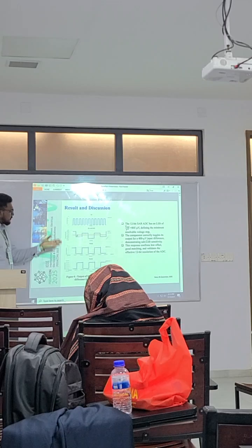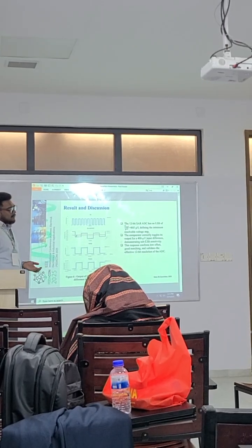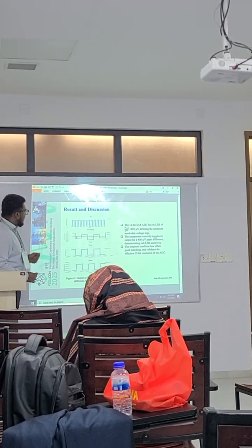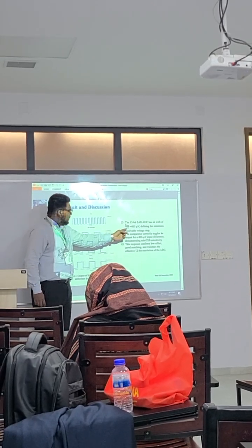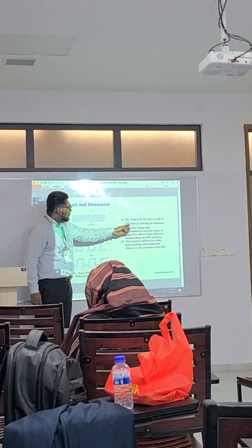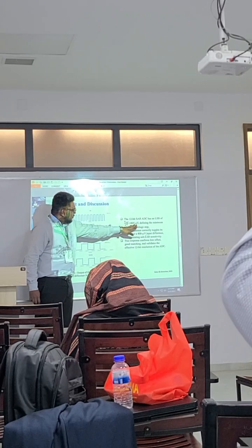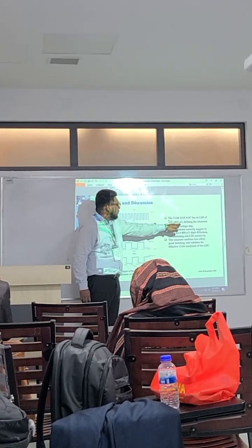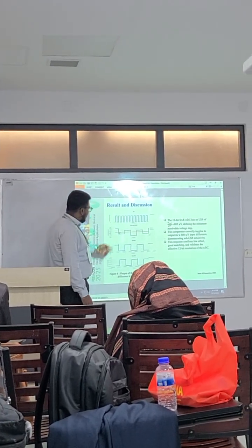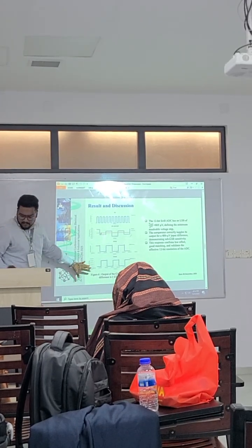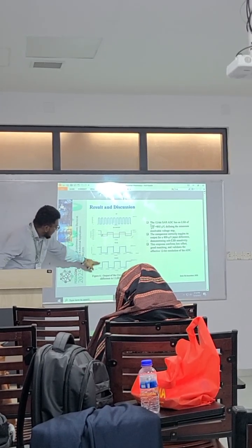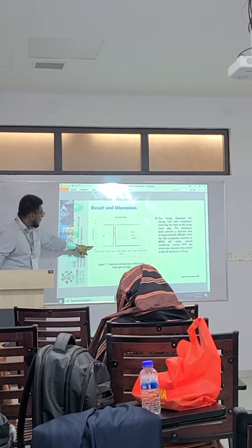So here's one of our results. Here's our results. So basically, the LSB has to be VREF divided by 2 to the power n number of bits. So we have to make this comparator work in 805 microvolt, and this is the depiction of it. The latch can take decision properly.